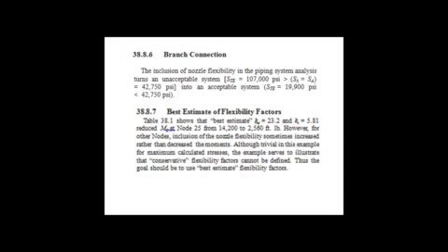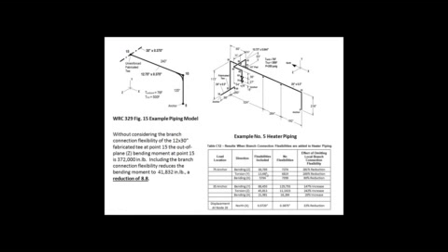So let's go see what conclusion Ev Rodabaugh drew for this system. When he analyzed this, according to Section 3, it was unacceptable. The stress was 107,000 psi without flexibilities, and it was easily acceptable. The stress was 19,900 psi when he added flexibilities. Now, Rodabaugh also stated something that was interesting, I think, about flexibilities, because he states that conservative flexibilities cannot be defined. Thus, the goal should be to get best estimate flexibility factors. We do see customers run FEA tools on every piping system. Now, we don't recommend that, but you can certainly do it.